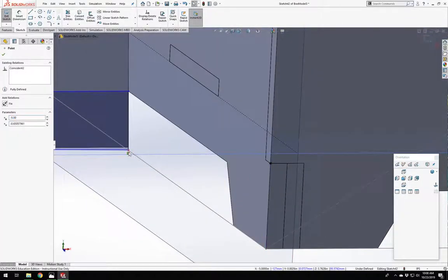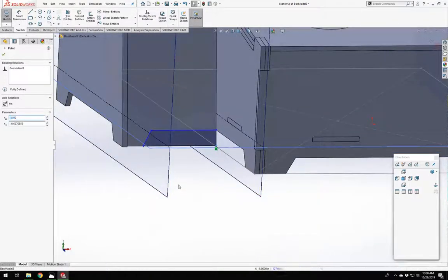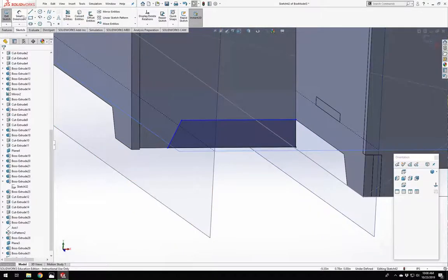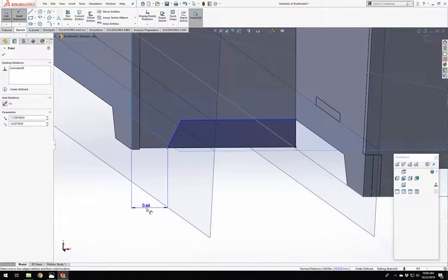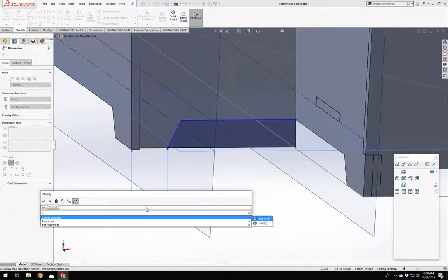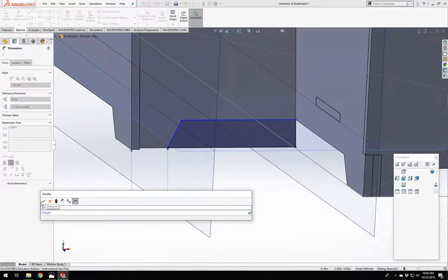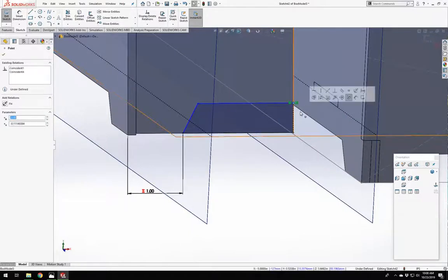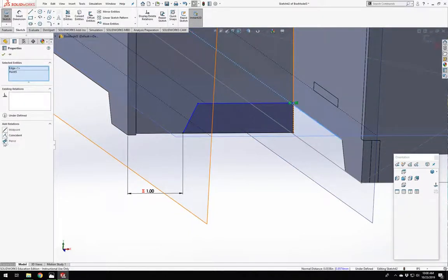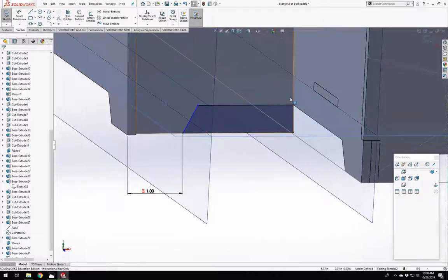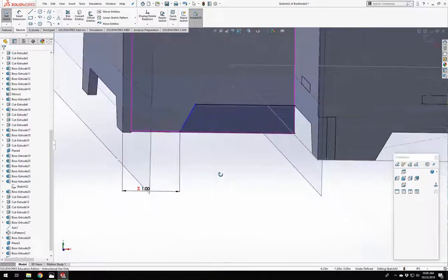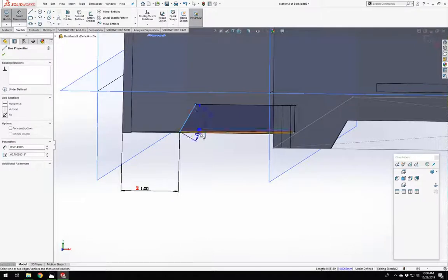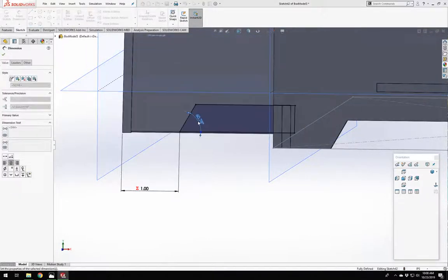That point is coincident to something I don't want it coincident to. There we go. And so this distance from this point to that edge is going to be equal to our global foot variable. There we go. And this point, we're going to line up with that. And we're going to use pierce in this case, as we want that point to go basically through there. And we also know that this angle is 60 degrees.